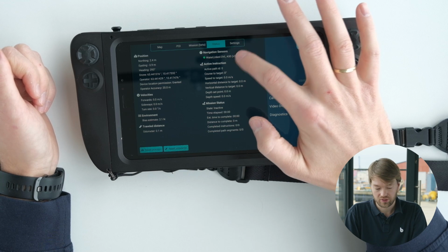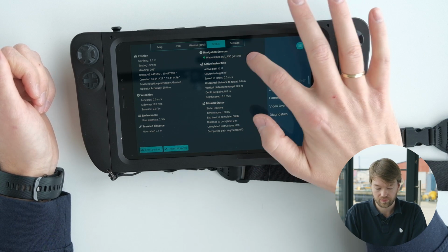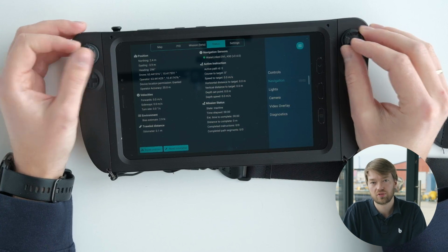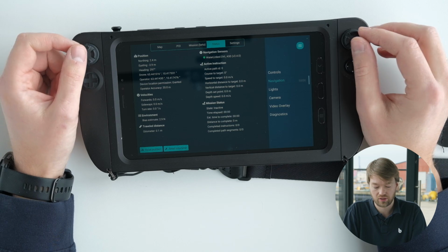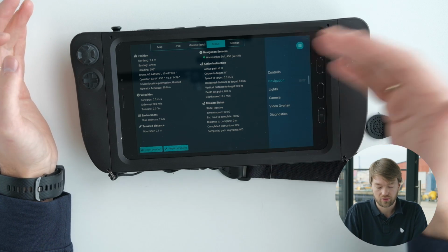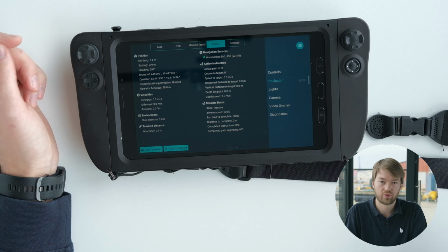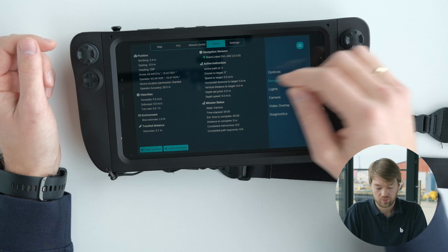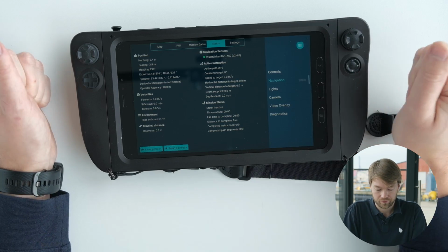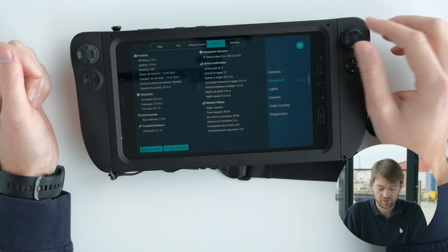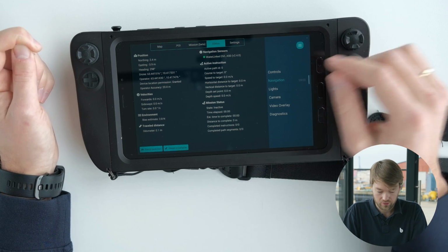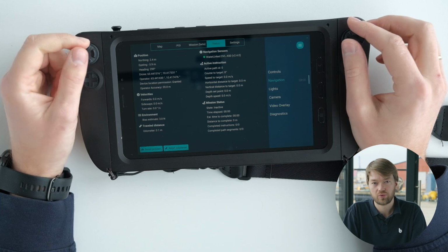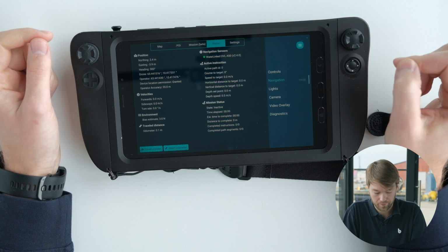On the top right here you can see navigation sensors. It will list out the connected positioning systems. So in this case it's only the DVL A50. But if we were to connect a UGPS from Waterlinked or an NMEA device with USBL positioning systems, they will also get listed here. And the green light is indicating that it's valid. The two last sections are related to the mission planner, which is covered in a separate video.